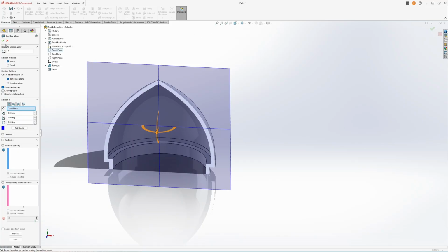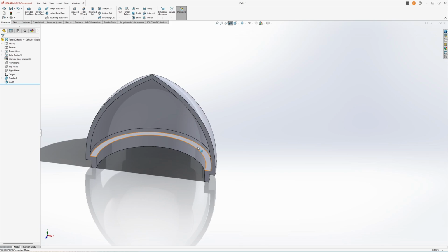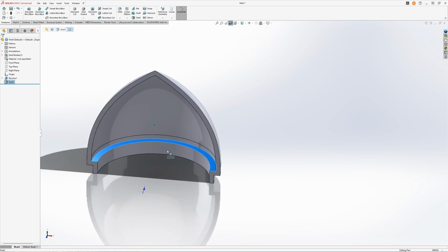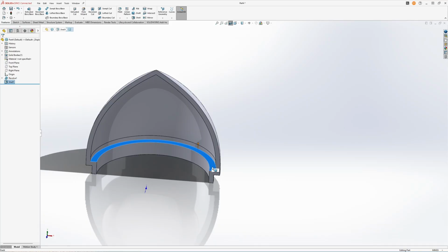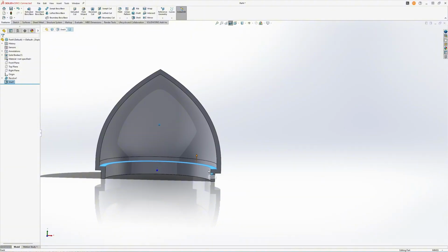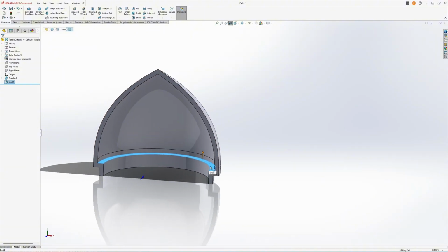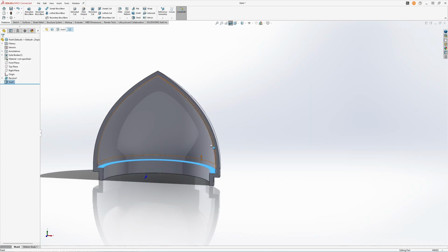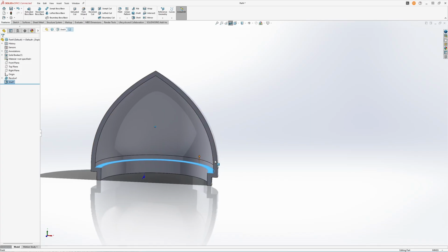take this section view so we can see what we're doing. I'm gonna select this surface in here. Because what I want to try to do is I want to basically extrude or fill this surface, this internal space here in the right. And one way to do that is just to create a sketch that has that area, but extruded that way until it meets this geometry.